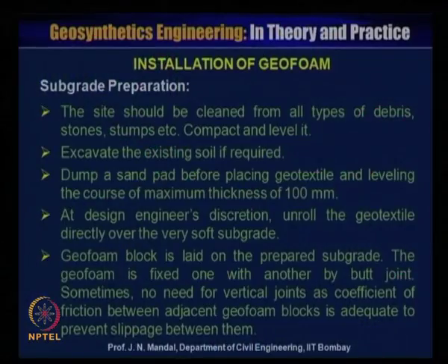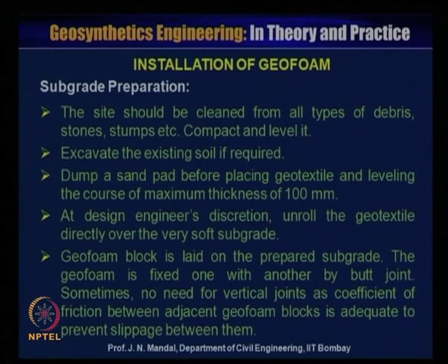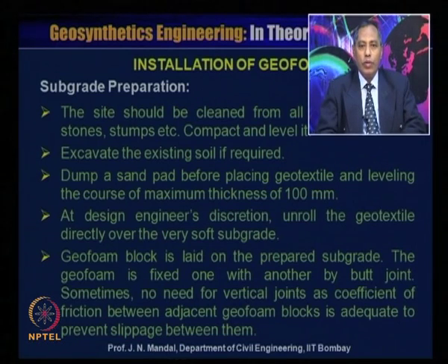Now I will discuss the installation of the geofoam. Now you require subgrade preparation. The site should be clear from all types of debris, stone, stumps, etc., and compacted and leveled. Excavate the existing soil if required. Dump a sand pad before placing geotextile and leveling the course, of maximum thickness of 100 millimeter.